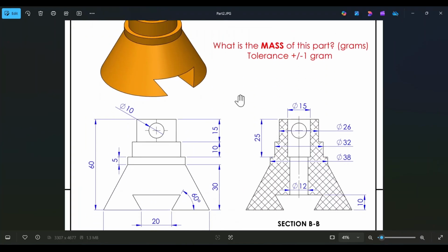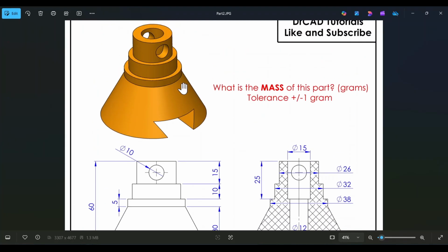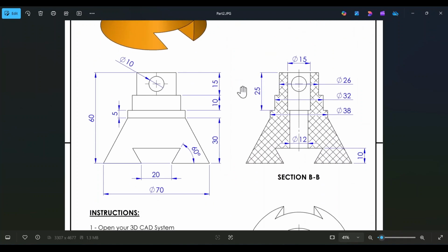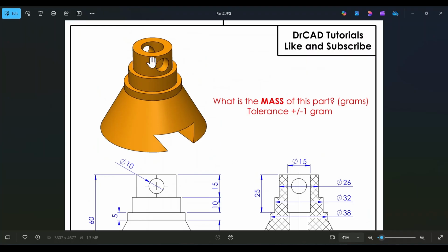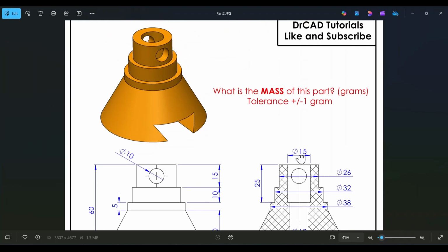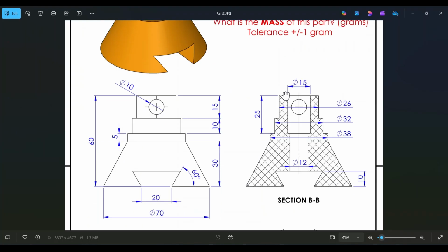Okay, so looking at the main features for the component here, we see that we have a conical body, right? And to create that within SolidWorks, I think the easiest way to do that is to utilize any symmetry that we have. And if we ignore any of the secondary features for the component, for example, the slot feature and this hole and counterbore feature, just for a second, we see that the component has radial symmetry, right? Along the radius for the component.